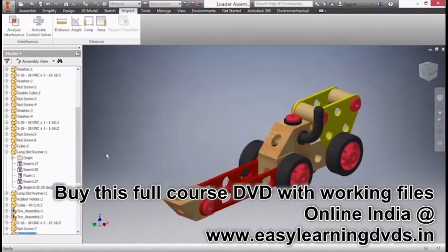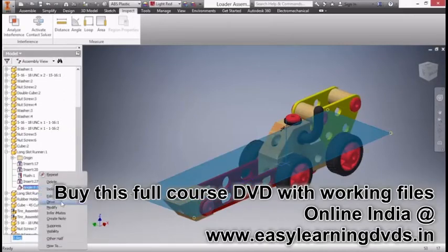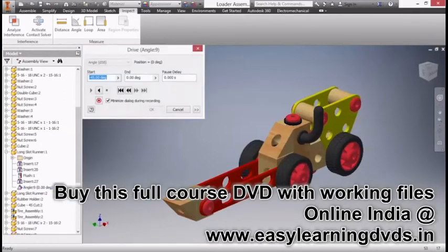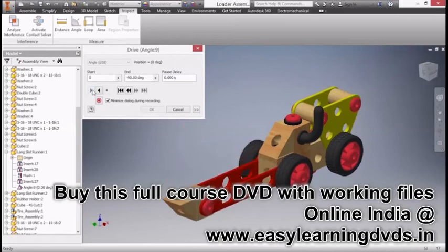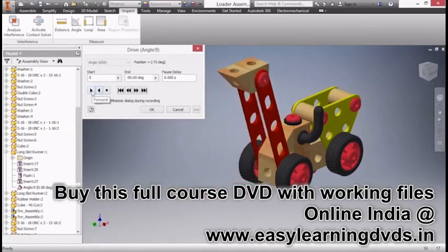Now if I want to see a visual change of that motion, what I can do is right click on the angle 9 here and choose the option called drive. This will take my constraint and drive it from one value to another. So I'm going to start here at a 0 value and end at negative 90. And basically just play this in reverse direction because I'm going in the negative direction or the positive direction, depending on which way you're going. And you can see that range of motion taking place.